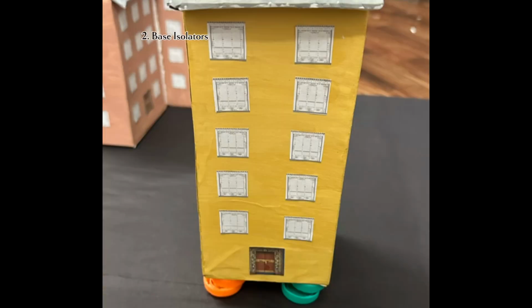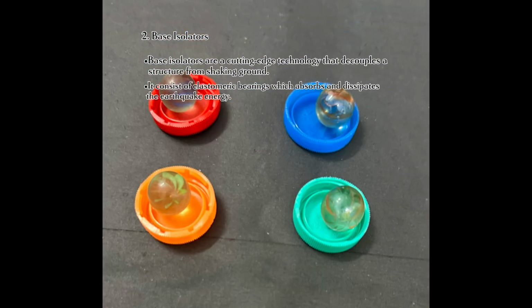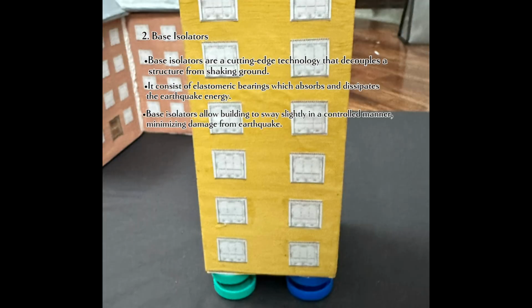2. Base isolators. Base isolators are a cutting-edge technology that decouples a structure from shaking ground. It consists of elastomeric bearings, which absorb and dissipate the earthquake energy. Base isolators allow the building to sway slightly in a controlled manner, minimizing damage from earthquake. Implementing base isolation requires specialized engineering expertise to ensure optimal performance.